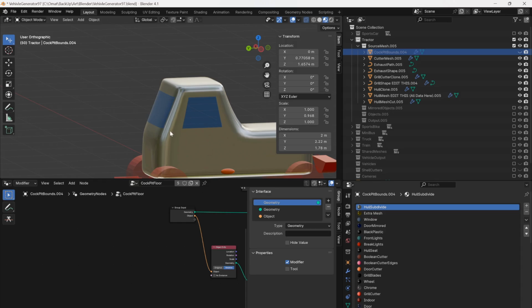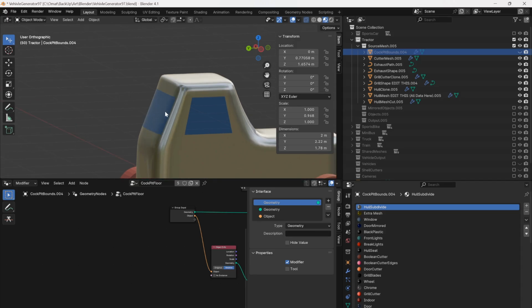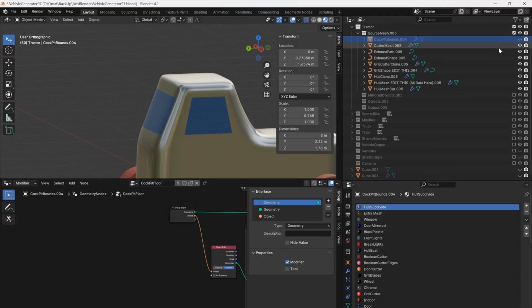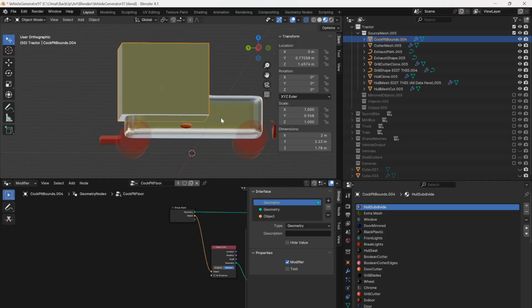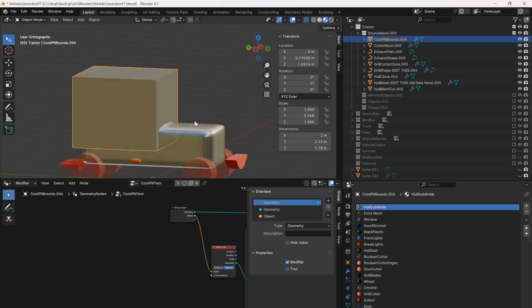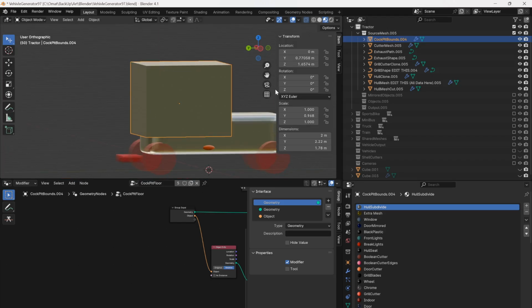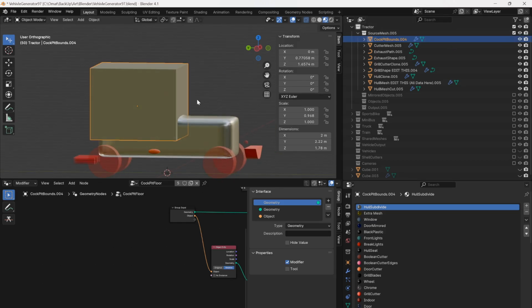The cockpit, everything will be generated based on this line here. This is kind of what drives everything. The window that is facing that way and the bottom of that defines the floor level, and it also defines where the dashboard will start. So everything can be kind of automatically generated.